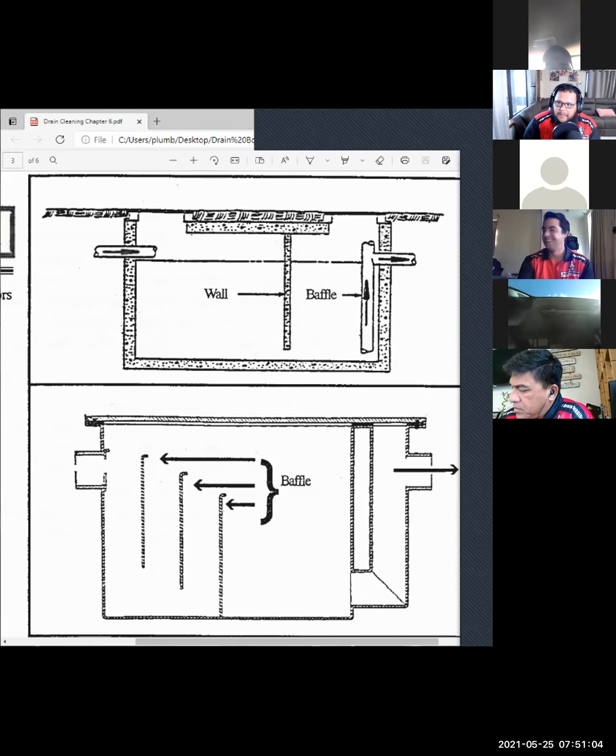Well, listen, you guys, it's pretty simple, but they don't do it. They're supposed to lay a tube in there and catch a flow, and then they send it into a laboratory, and it's a parts per million thing. I used to know right off the top of my head it was 100 parts per million or something, but it might be 100 parts per thousand. But there's supposed to be an acceptable level of fat content or FOG that's passing into the city sewer system, county sewer system, municipal sewer system. And if it's beyond that limit, then they've got to have better controls on the FOG, which means more frequent pumping, or it's undersized.